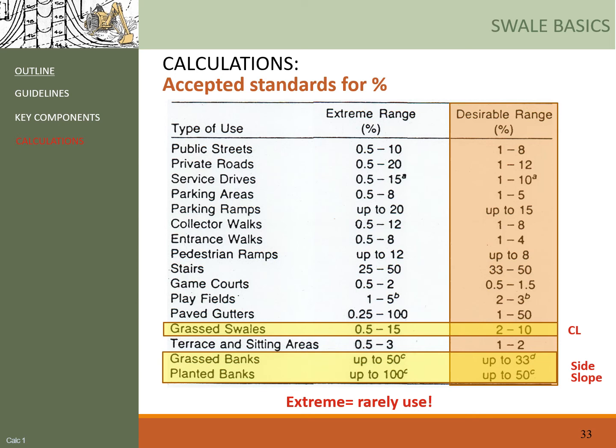Okay? And why don't we want to go steeper than 10% on a grass swale? The steeper the centerline gets, the faster the water moves through the swale, right? And then if you get fast moving water, what do you get next? Potential erosion, right? And it's very hard to maintain as well if your slope gets above 10%.